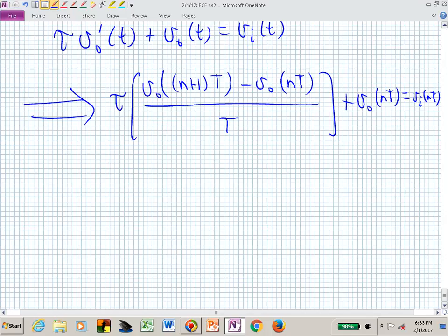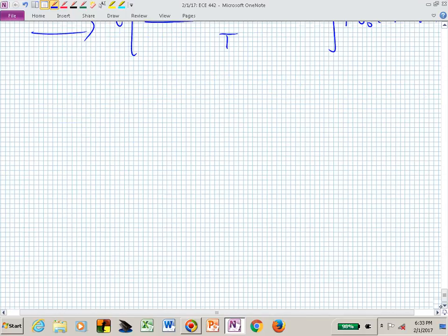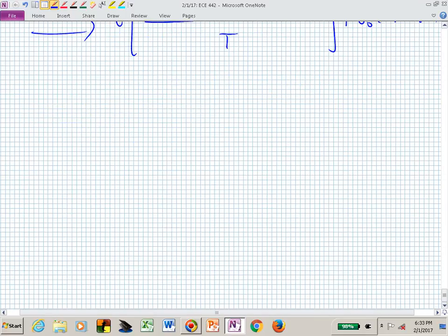So I've sliced this up pretty fine in terms of the time axis. Yes? So the question was, we approximated pi a couple of different places. Do they cancel each other out? Not necessarily. We used a pi approximation to approximate our bandwidth of the low-pass filter, and then we said, let's find our capital T, the sample period, and we approximated pi.